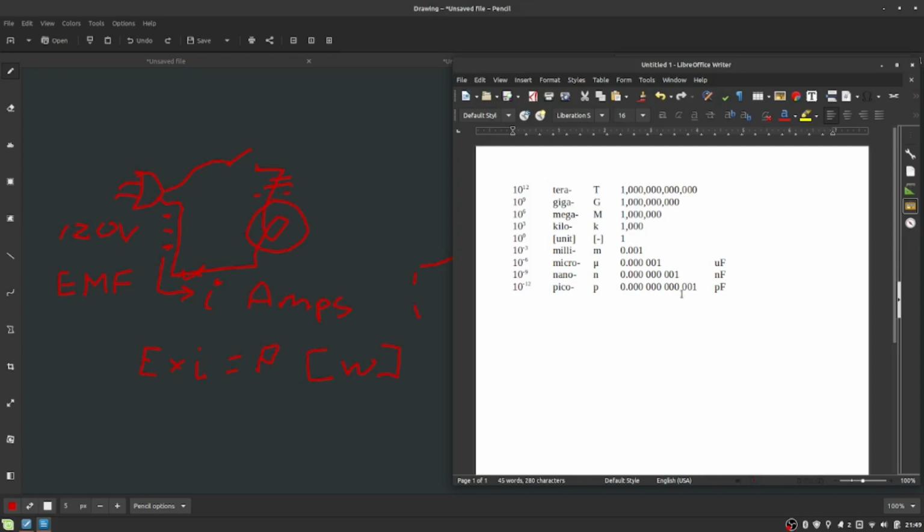So these are very common numbers, and it is also very important to be able to switch between these. One thing that you will run into a lot when you're dealing with ham radio is frequencies may be given to you in, for example, 1,400 kilohertz. And you have to be able to do the math quick and realize that that's 1.4 megahertz. Depending on your radio dial, that might be something you have to do on a pretty regular basis. Again, occasionally you'll get into the gigahertz range, especially if you're dealing with, for example, the 2.4 gigahertz frequencies. It's kind of shared with Wi-Fi and things like that.